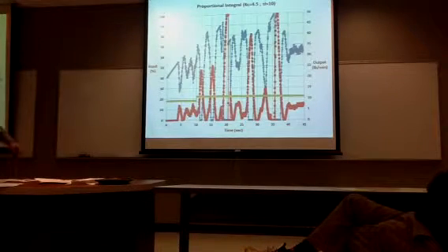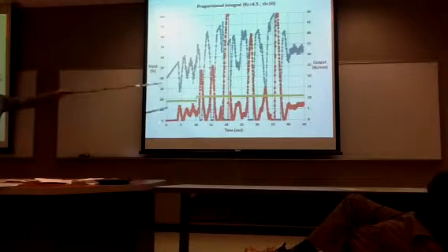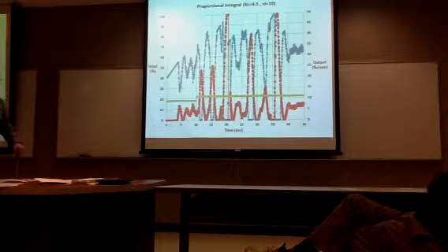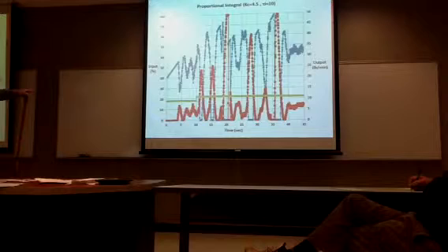When I went and did 4 times the tau I, it started jumping all over the place. It was going from 0 to 100 nearly, and it took 40 seconds for it to settle out. And this is going from the set point of 9 and then stepping up to 11 pounds per minute.